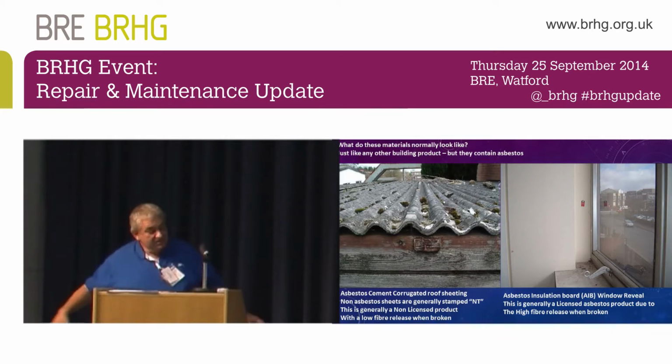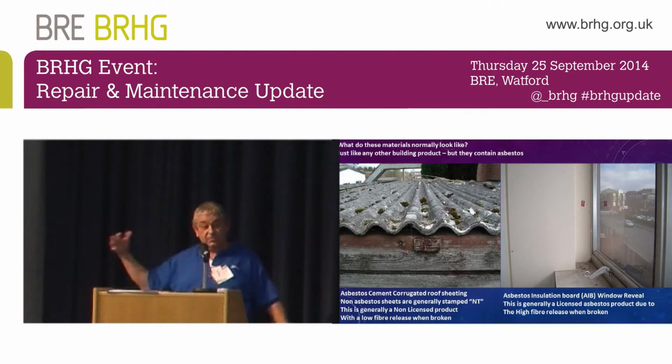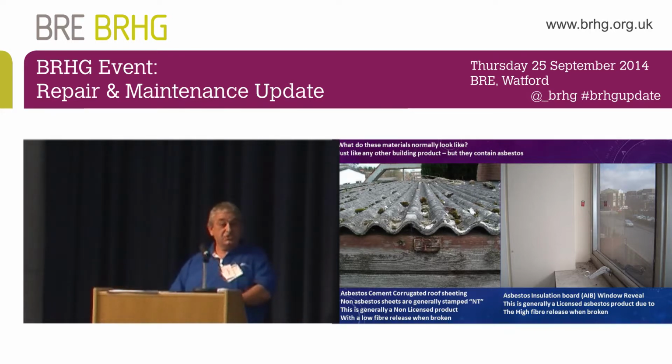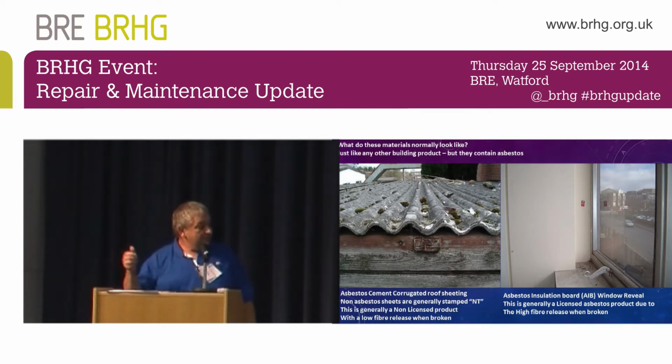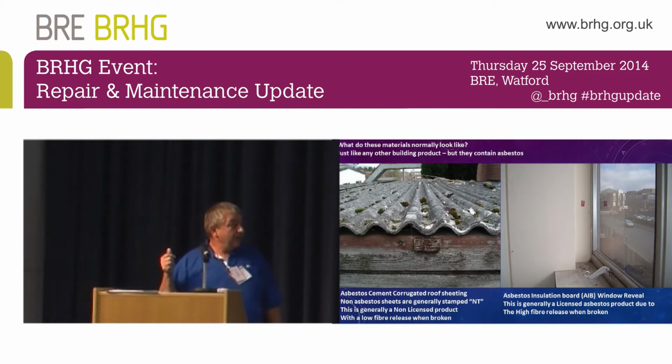So we placed air tests all around the site, all flagged so we could see the wind direction, because obviously the highest concentration of fibre is going to be downwind. And that was okay, but HSE came down, yeah, we're happy with that. I said, well, I'm not happy. And so I got the guys to fix up spray wetting booms on their diggers.